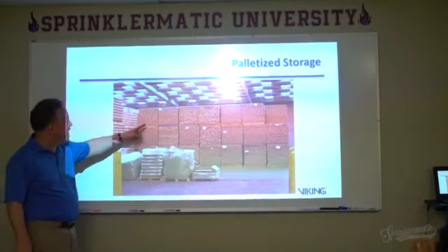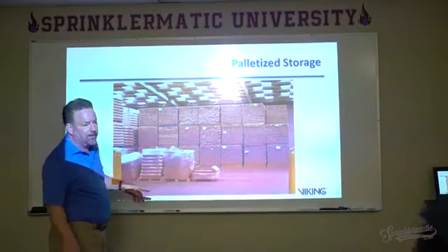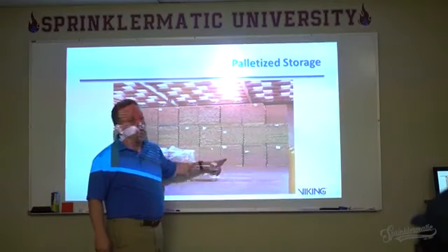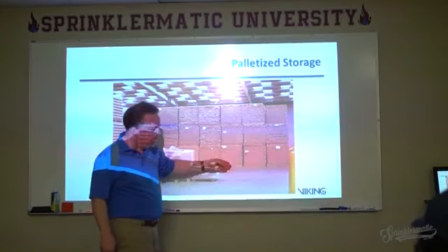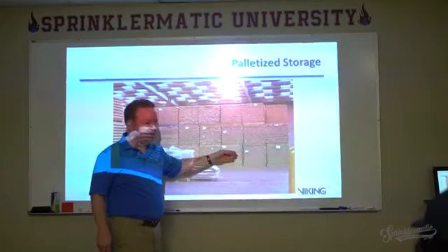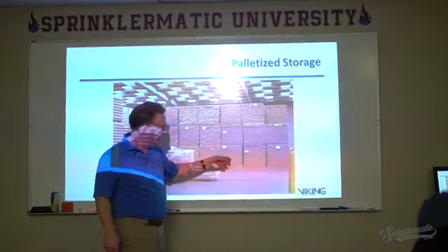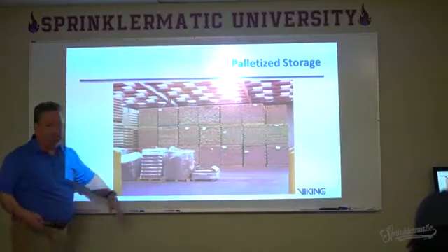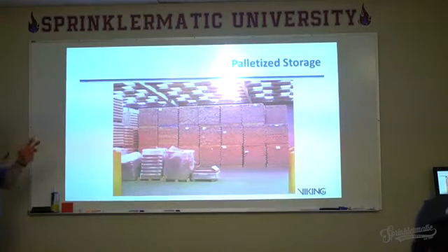And the reason that we look at it that way is because we don't have much space in between here. And so if we started a fire out here on this material, it would take a really long time for it to get going. Because all it would be burning would be what's on the surface. Okay, very difficult to get it in here. Once it gets in there, it's pretty stubborn, but there's not a lot of oxygen drawing it or allowing it to get in there. Okay, so that's one way of looking at it. That's what we call a closed array storage arrangement. In other words, the closed array is there's not a lot of air that moves around the commodity.